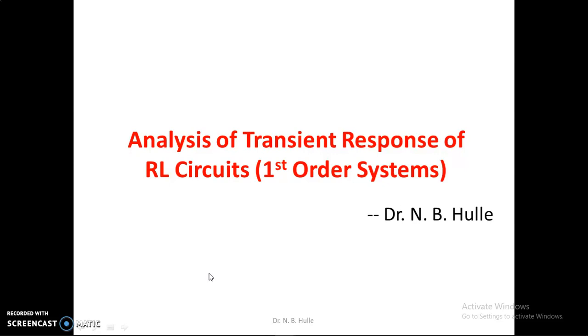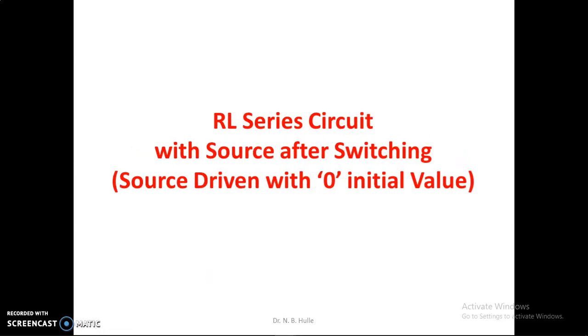In this video, we will try to understand analysis of transient response of RL circuit, that is, the first order systems. Here, I will divide this analysis into three parts. One is source driven with zero initial condition. Second one is the source free, and third is source driven with some finite initial conditions. First, we will start with the source driven with zero initial conditions, that is the transient response of RL series circuit.